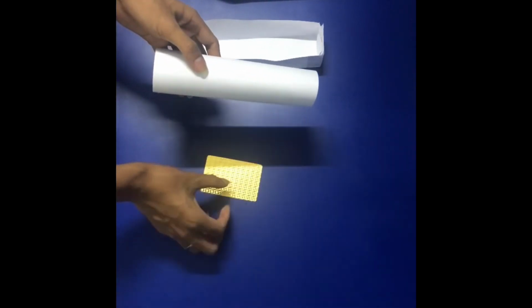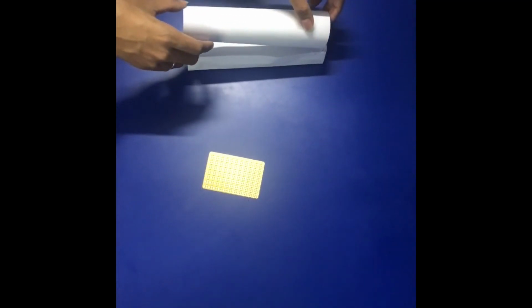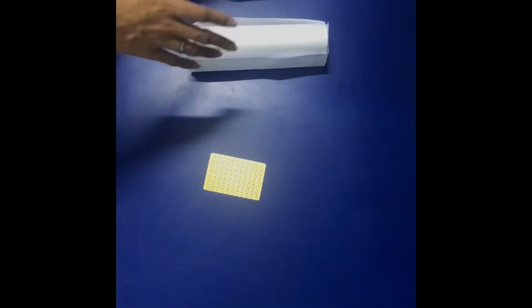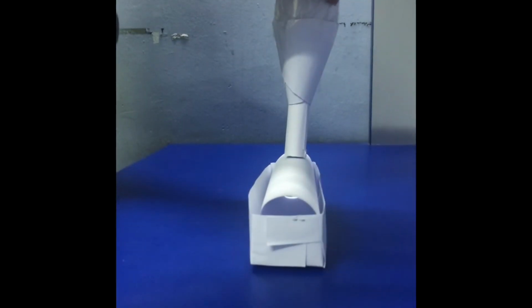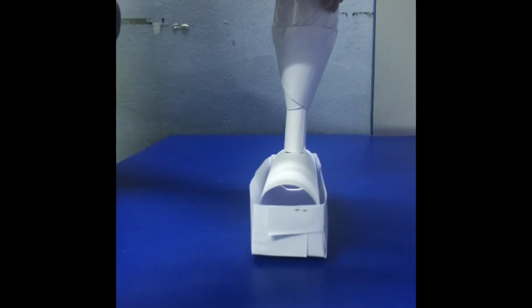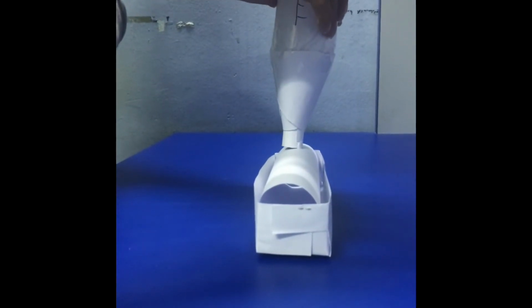After that, the core sample will be clamped onto the steel cradle, which will avoid vibration or movement while the experiment is conducted. We need to compress the hammer spring by depressing the plunger perpendicular to the specimen until the hammer is triggered and the impact occurs.